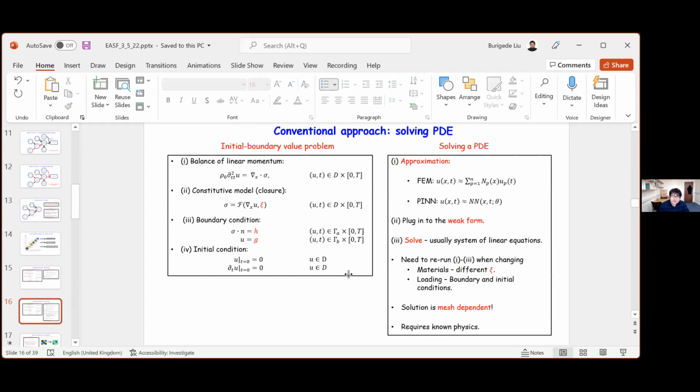The solution procedure is basically similar to what one would use in FEM. Rather, you just use the PINN, and you can naively just use a gradient descent method to minimize the PDE loss, and that's what PINN does. There is also some recent work where you can design scalable PINN by combining everything PINN proposed with what the FEM people have done for the past 30 years.